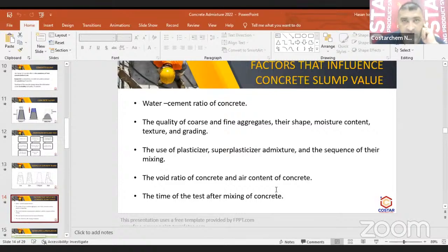So to release the stresses exerted by the increased size of the water inside the concrete, these small bubbles will relieve the concrete. The excess volume will just go into these bubbles, and it will enhance the durability factor of our concrete dramatically.